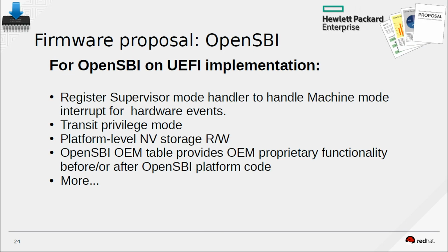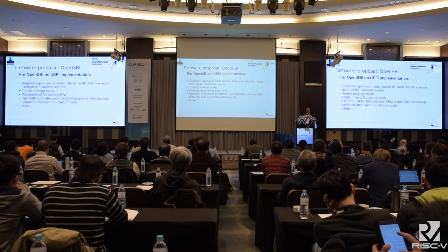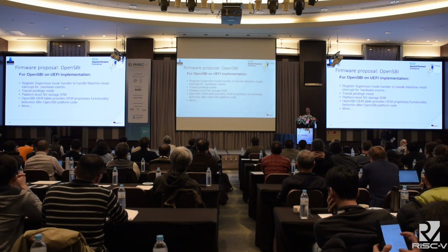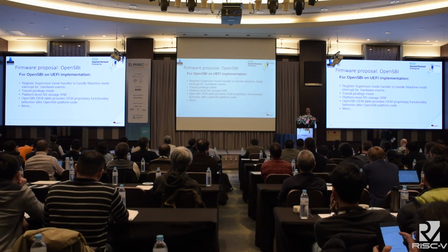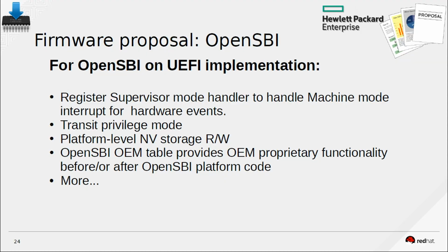There are some proposals for OpenSBI. We need functions like registering a supervisor mode handler to handle machine mode interrupts for hardware events. We also need to transfer privilege mode in platform level, variable storage read-write functions, and some other functions.